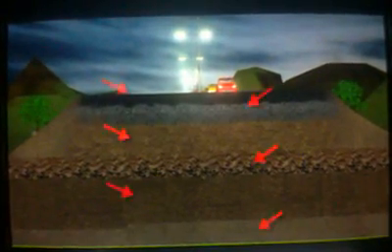Highways are subjected to a high level of traffic stresses regularly. The vertical compressive stress is maximum on the pavement surface directly under the wheel load and is equal to the contact pressure under the wheel. Layer system concept was developed for stress distribution on the flexible pavement.